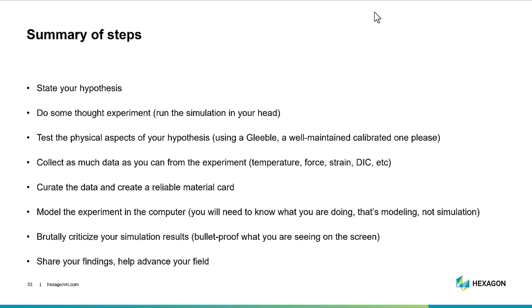You won't be able to use raw data directly in the simulation, so you need to do some data curation. It's not hard at all. You need to filter the data, for example, use Origin or create a curve fitting, and then use that curve as input for your simulation. That's an important step because you need to trust the input data that you have for the numerical model.